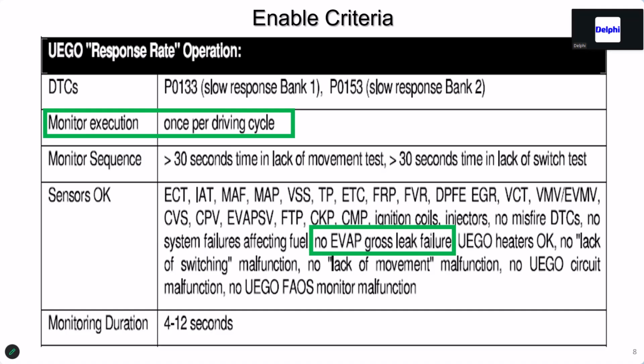If I go look up the criteria for a P0133, I find that this is the one that's holding me up. Okay, now you always want to take a look at sensors, and also no conflicting DTCs. Example of this one I'm going to show you throughout this series is EVAP. In this particular case, it is an issue. It can keep the O2 from running.